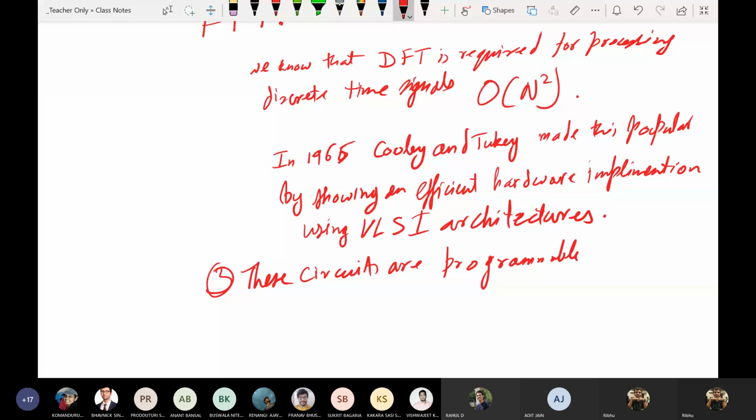so you want to suppress certain frequency bands. You need to derive a band pass filter. A complicated process. You have to have the exact inductances and the exact resistors, right? Yes. But instead, if you decide to process the same signal digitally, you can convert it from analog to digital, take the FFT, use a simple numerical filter and get anything you want.